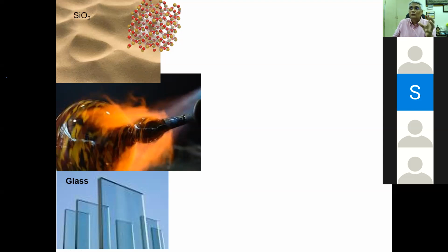So if you really want to achieve quenching, where you don't want to give any time for the atoms to settle down to their lattice positions, you can quench the melt into ice, 0 degrees centigrade. Boom, you drop it, or into liquid nitrogen, right? Ice is the best example, affordable. And now I have a liquid nitrogen bath. I drop this melt into a liquid nitrogen bath, so I'm not allowing any time for the melt to naturally cool down to room temperature.